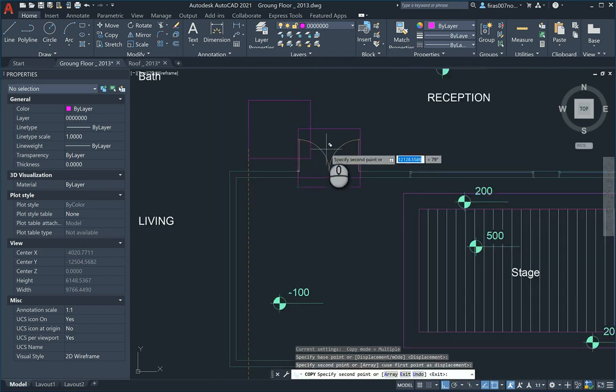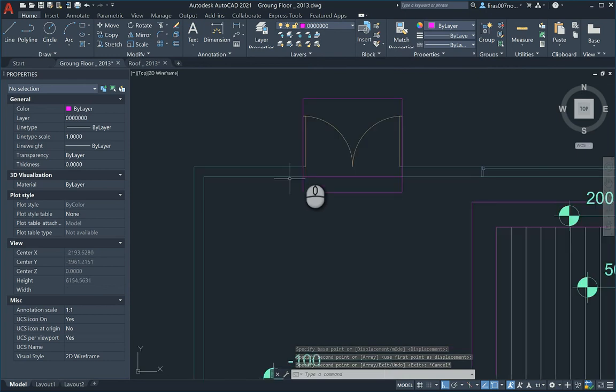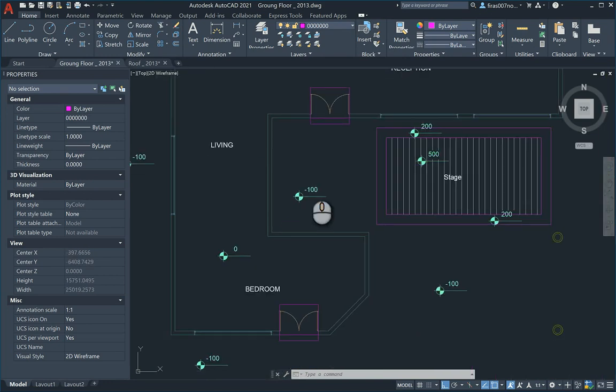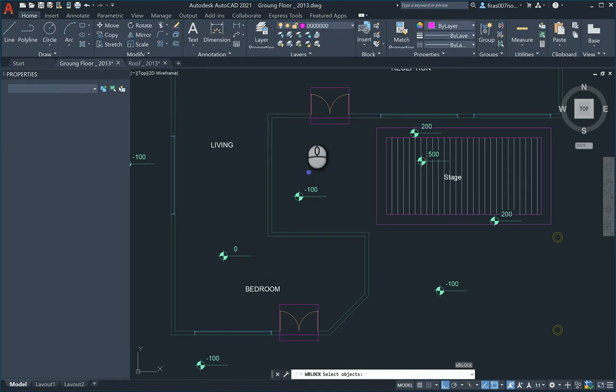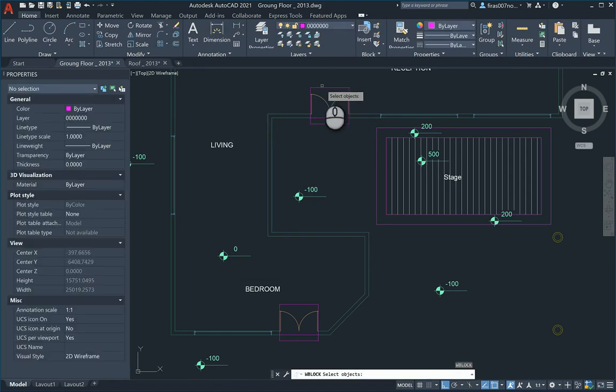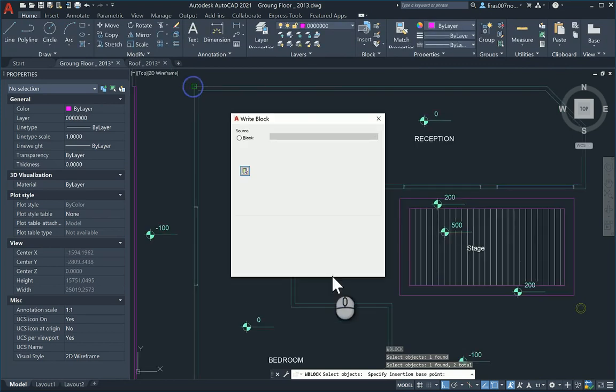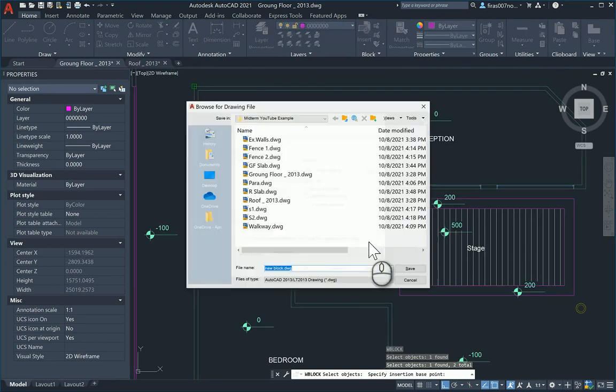Make sure that this box is as big as you can compared to this one, so it should be fully penetrated it and should be bigger than that. Don't make it smaller and don't make it flush. Don't just trace the edges of the wall here. The rest is self-explained. The steps that we keep doing a couple of minutes ago. The base point is the same base point, nothing changed, and just say that this is the door opening.